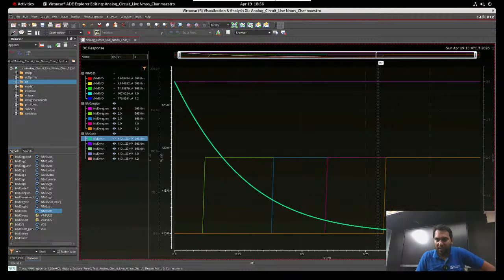Yes dear, if time permits, we will work on the layout also. We provide complete analog and layout. Okay sir, is this same concept applicable to flip flop? No dear, in digital we never talk about the region. In digital we always talk about switch on and switch off. There is no requirement of linear, saturation, cutoff; we only talk about cutoff meaning switch off, and on meaning switch on. If you require linear and saturation, you can talk about the delay.